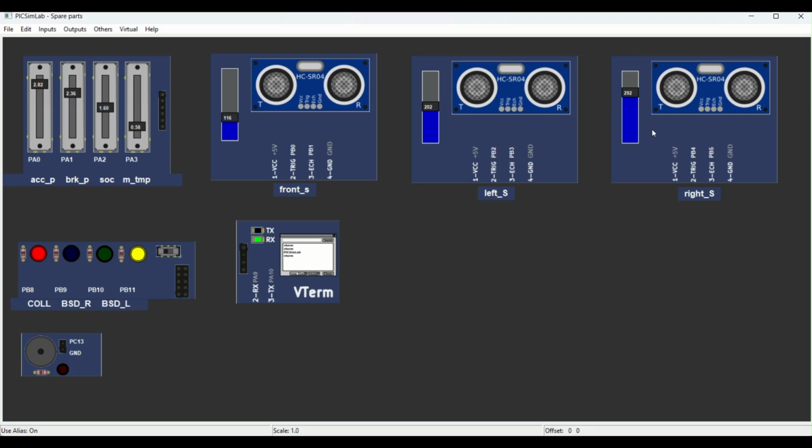Each sensor block features an adjustable slider right next to it. By moving these up and down during testing, we can simulate an obstacle coming closer to or moving away from our vehicle, allowing the STM32 to calculate the time to collision in real time.